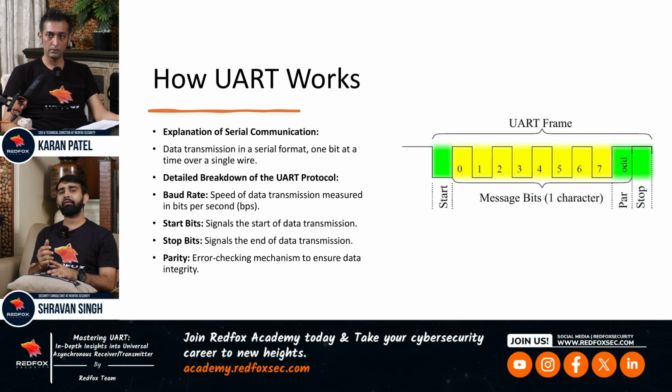And the most important thing is the baud rate. If you have a device and you are connecting it with the terminal, and you don't know the baud rate, then there will be a big mistake, because the data will not be displayed as per your need. If you know the baud rate, such as 9600, 115200, or 57600, it depends upon the baud rate how the device functions.